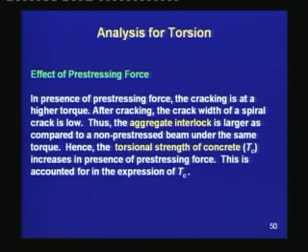In presence of the prestressing force, the cracking in the concrete occurs at a higher torque. That itself shows that the concrete will have a higher resistance to torsion in presence of the prestressing force.